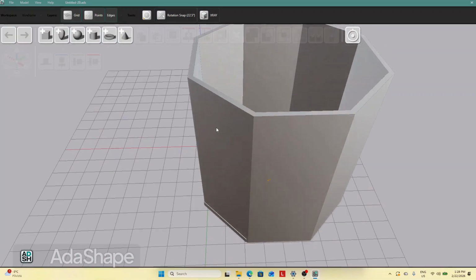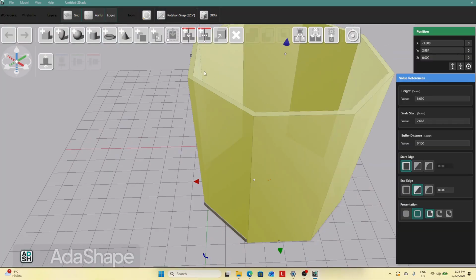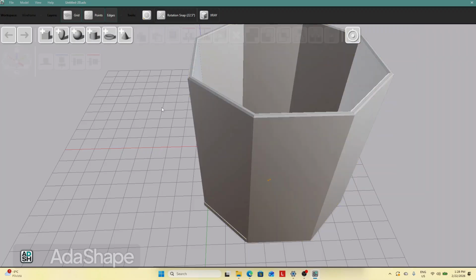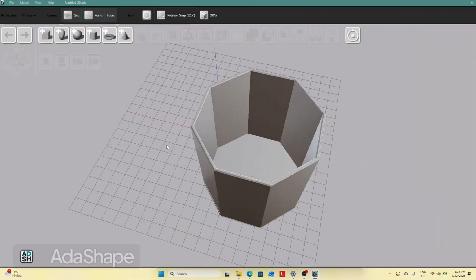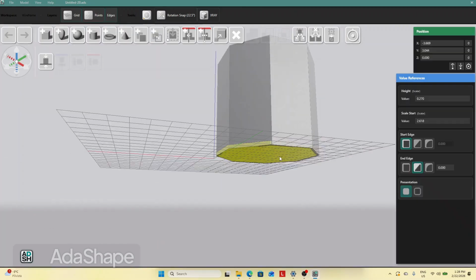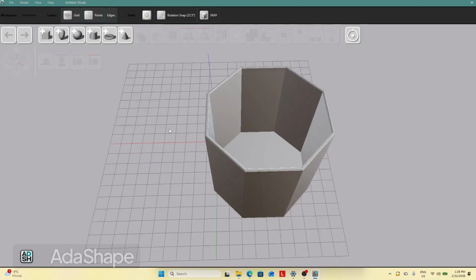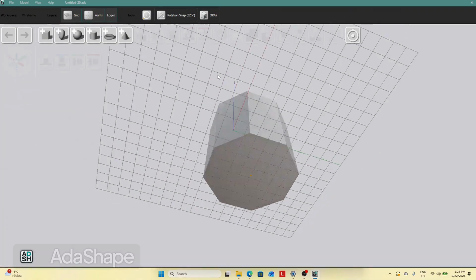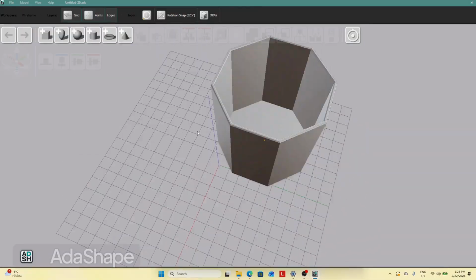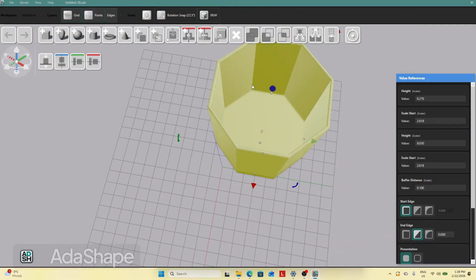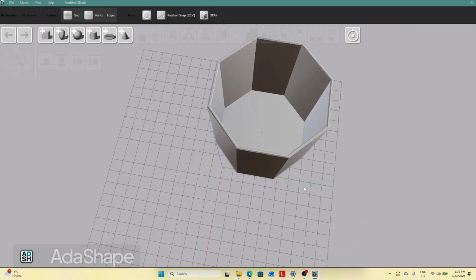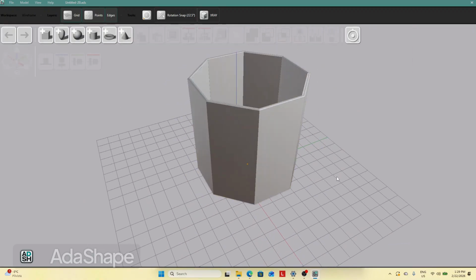They are a bit rough maybe from the top, so let's see if we can add some edge treatment over there to make it slightly smoother. And now it's too sharp, I don't like it. So let's just make it... All right, there we go. It's nice and smooth. And you notice that we have this base plate over here. So let's put them so that they are aligned like that, and they're one single shape. So now we can bind them into a single shape using the union.